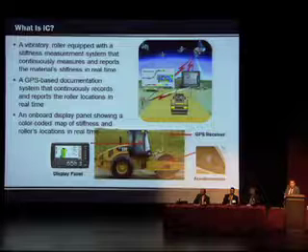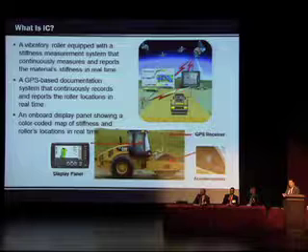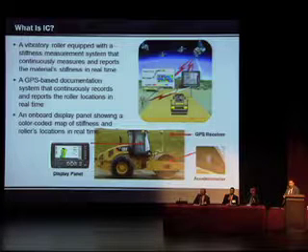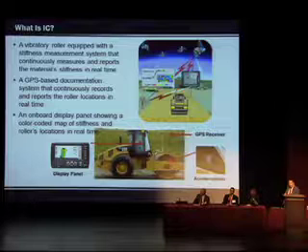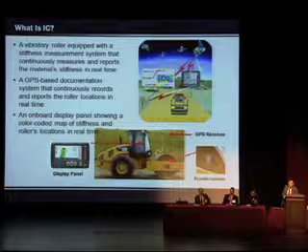Then he will be able to see where he has compacted, where he has not, and how many passes he has made. Has he reached the stiffness or not? This is nothing to do with the density, okay? It's a stiffness-based measurement.